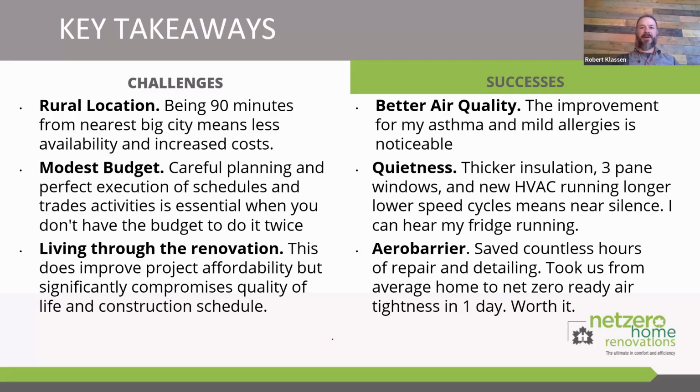Amazingly, due to solar gain and the improved envelope of the house, we'd only had a temperature drift of about 2.5 degrees in 6 hours at a 40 degrees Celsius delta. Turning the heating system on for about half an hour and the HRV on boost for 2 hours made all of the condensation disappear, because we had gotten up to a relative humidity of around 65%, and in 2 hours it was back down to 45.